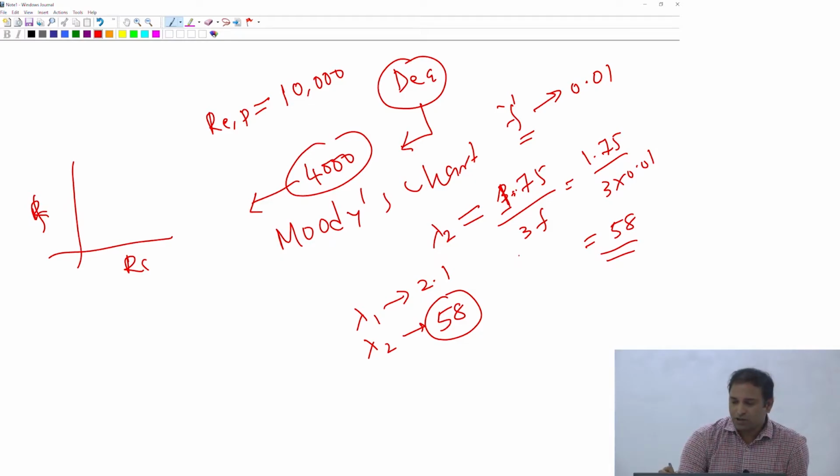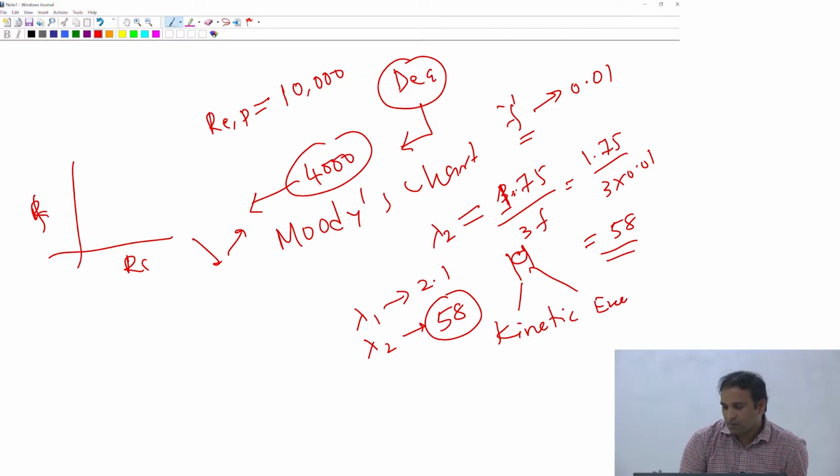That means in some channels the fluid is going to be flowing in a channel of particular area, and there could be expansion of the liquid at some locations, plus the fact that liquid is going to turn the direction in which it is flowing. All that leads to much larger kinetic energy losses, and you can think about that in terms of the larger value of tortuosity.